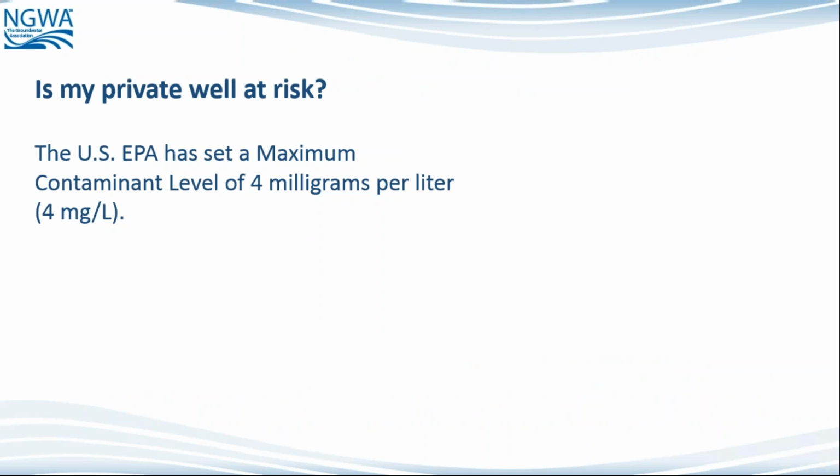When we think about fluorosis or fluoride in our water and either the benefits or the problems caused by it, we do have stipulated by the US EPA what we call primary drinking water standards. Under those standards, we have certain parameters that we consider a maximum contaminant level, or an MCL, as you might hear us refer to in the water industry. For fluoride, the maximum contaminant level for municipal water districts is 4 milligrams per liter, or what we might refer to as parts per million.